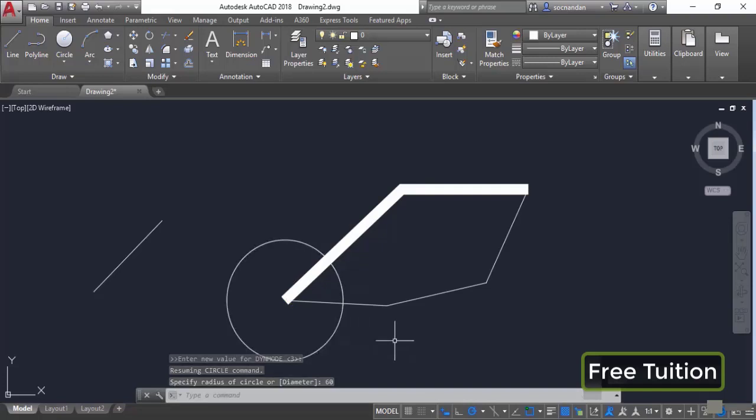So in this way, you can use the dynamic input option for bringing your command line directly on the cursor. That will decrease your dependency on the command line, but obviously it is not a replacement for your command line. Command line will be required for many other situations also, but you can use it wherever you find it most helpful. So I'll just click on this option once again to turn it off, as I prefer working with it off.